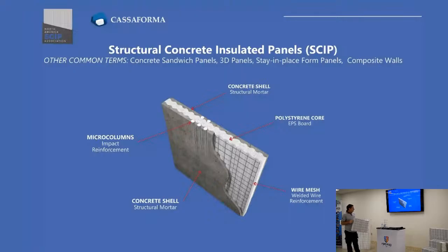So what we have to understand is that the mesh provides us with all we need for two things. The first thing is that the mortar gets thick, okay? So it's a place where it can receive the mortar, okay? The other thing is that the mortar will be protecting the mesh as well. Okay.